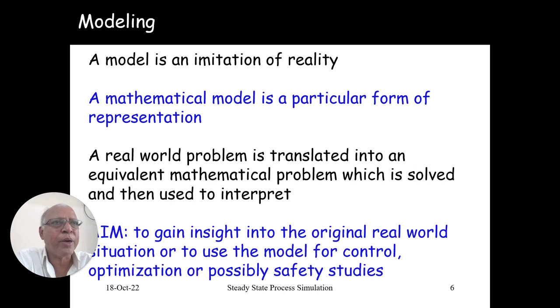So just because you are not permitted to experiment, do you think we should give up this particular topic? Optimizing temperature, if you are able to improve the conversion, probably you may be able to improve your profit. So just because you are not in a position to experiment, you need not give up this particular problem. Now let me identify the three important things that I was talking about whenever you think of modeling. What is the system that I have in mind? Let us consider the particular type of reactor which is in operation in an existing plant. It can be a CSTR, PFR, or maybe any other type of reactor. So that is the actual system.